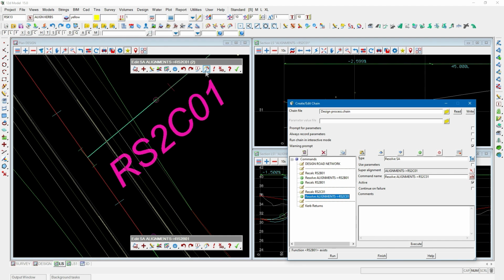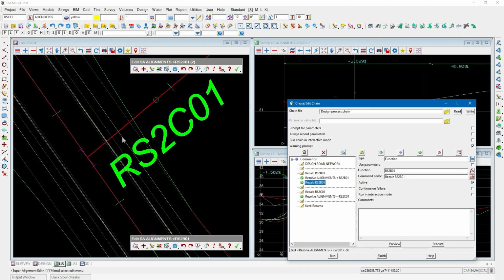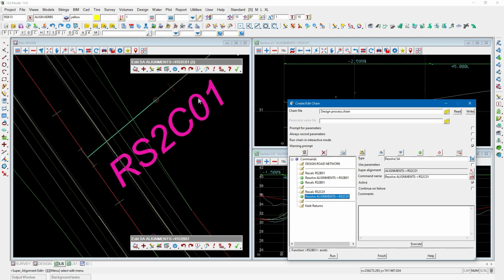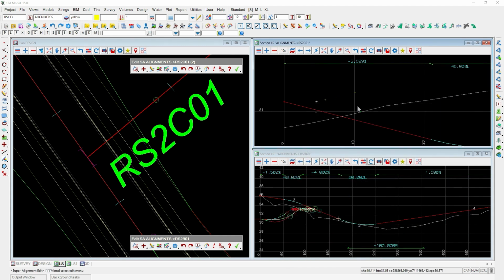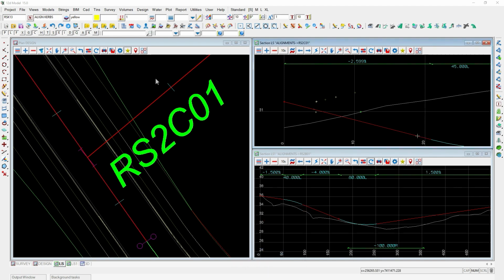So now the two roads are essentially locked horizontally and vertically. We just need it to calculate in this order to resolve the first road and the strings. And they're important because that's going to set up the vertical geometry for our side road to then pass on the information there as well. So that's how we would actually put the process in a chain and get the geometry to be solved. As another example, I thought we could also move across to an intersection.